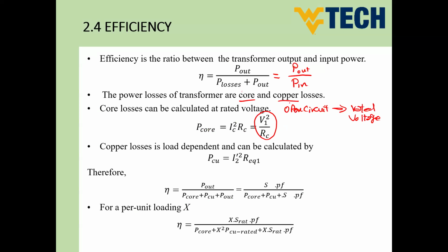It's not exactly constant because you know that V1 can be changed with the current magnitude according to the volt regulation we have, because it depends on the load current and how much voltage drop we have inside the transformer. So V1 would be changed as well. However, changes in V1 can be neglected, especially if the regulation is good on the circuit and the impedance is minimum in our transformer.